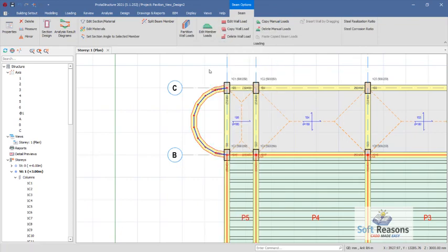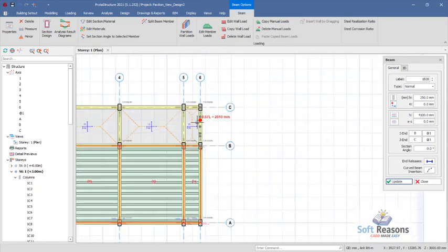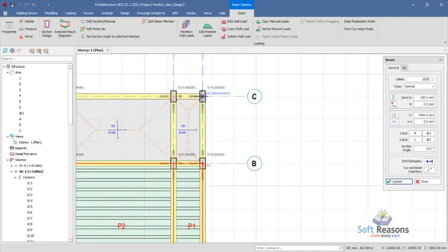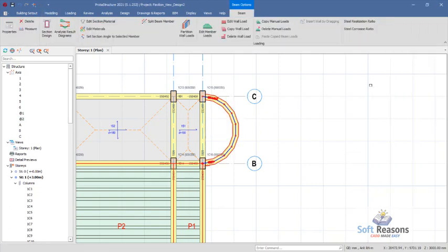You just click on its property and then come over to this side, hit on the intersection of grid lines C and B, right there, move your hand this way. Sorry, I have to pick the insertion method to be curve beam. So pick the first point, pick the second point, and then shift F2 to have a provision to key in the radius of the beam right there, like this. Close options.